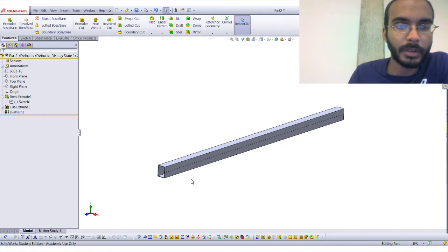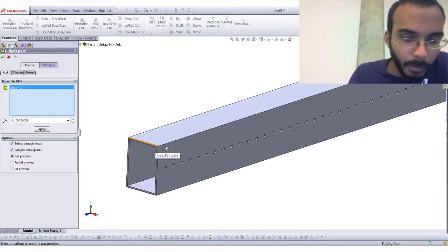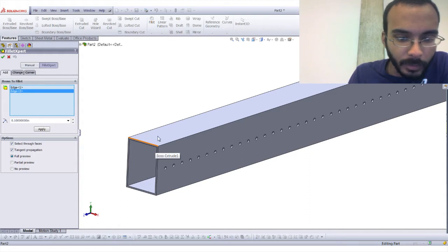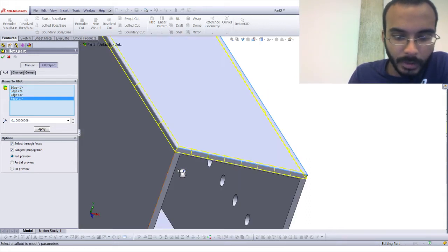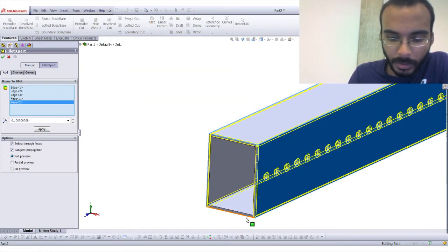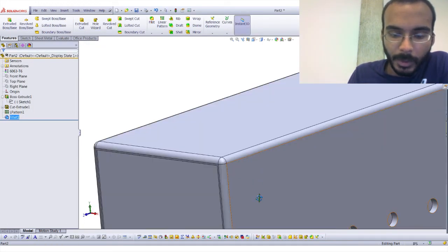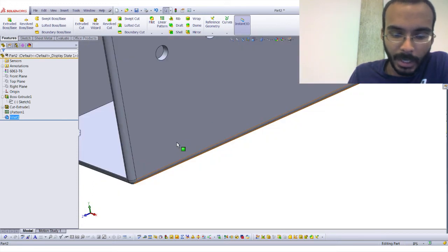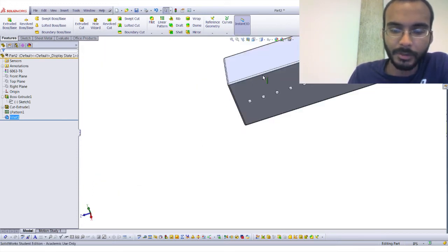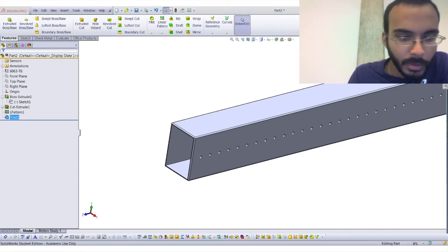The other really useful feature that we'll use a lot is called fillet. So we had sketch fillets before, but now we can select many different edges on a three-dimensional part, and you can tell them all to be the same dimension. You can select whole faces, and it'll select all sides of it if you want to, and you can make nice rounded corner bits, especially on parts that are going to be sanded and things like that. You don't want to cut people. On a piece of extrusion, probably not necessary, but on parts that you actually make, you definitely want to put fillets and nice round corners and things in.